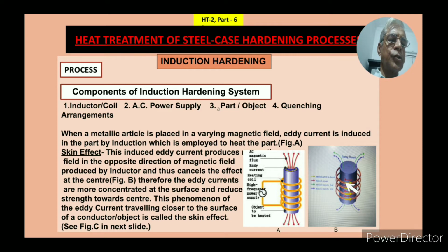opposite. So the eddy current, you see all the pink lines going in this direction, and this eddy current also produces a varying magnetic field, which is in just the opposite direction to the primary. So if the green, which is the primary, is in this direction, the magnetic field created by the eddy current is this. It is just in the opposite direction.